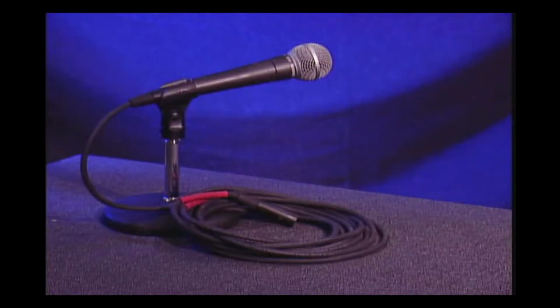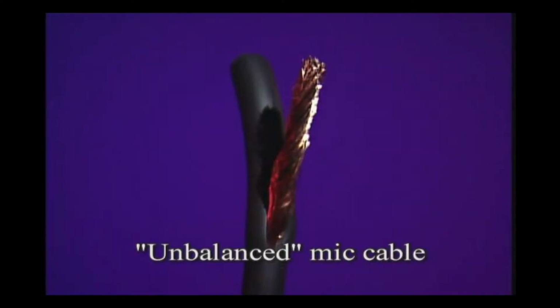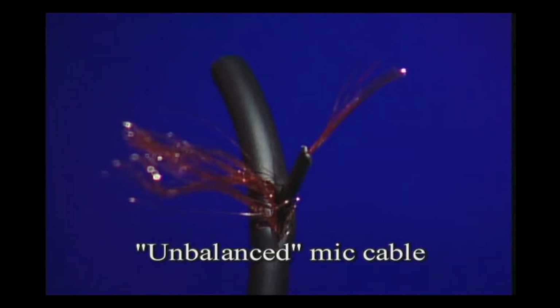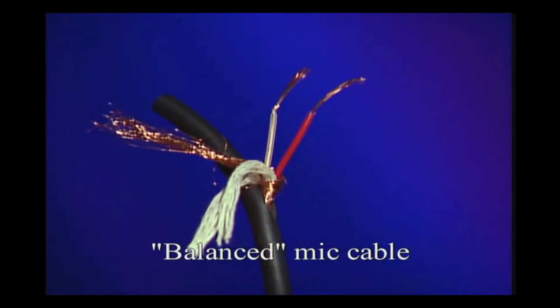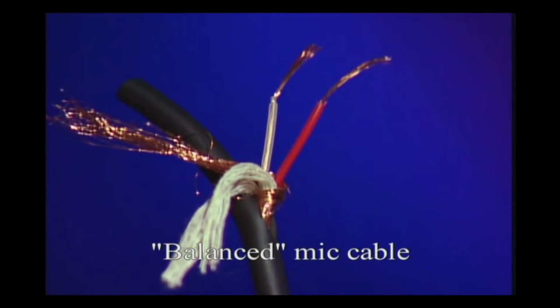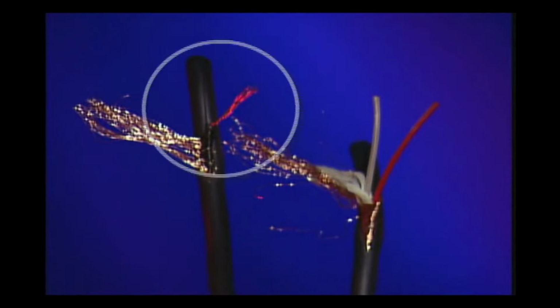Microphone cables carry the audio signal to its destination in 2 basic ways. Unbalanced cables use one of the signal-carrying conductors as a shield against electromagnetic interference. Balanced cables use matched signal-carrying conductors with a 3rd conductor surrounding it as a shield. Although unbalanced mic cables are cheaper and reasonably effective over short distances, there are 2 disadvantages.